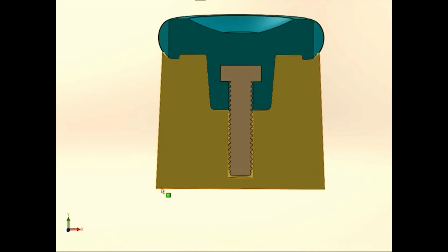So it's going to start building model material down here. It's going to start building this hole. The screw's not going to be there. We're going to have to delete the support material that it's going to put in this place, because it would need support material once it gets up here to draw upon it. So we're going to have to delete the support material.